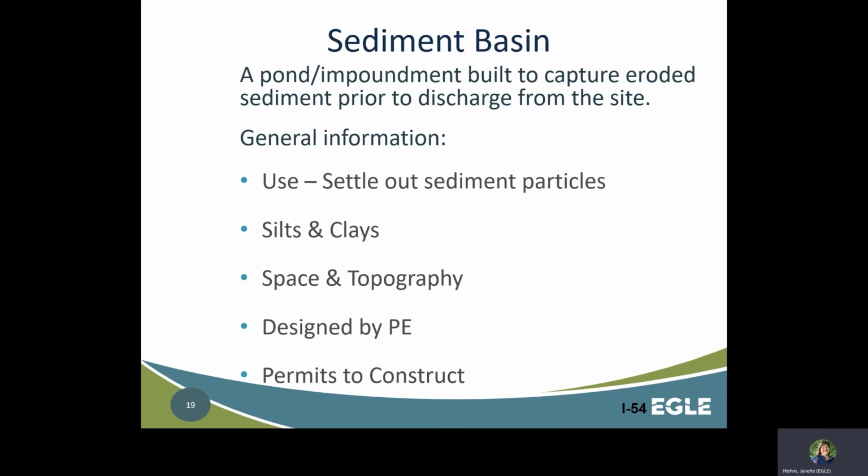Sediment basins can be effective for removing particles of sand and larger particles of silt. But what about smaller particles, including silts and fine clays? These small particles of sediment do not readily settle out in a sediment basin unless they have some extra help. Chemicals called polyacrylamides or PAMs are often used when fine silts and clays are present at the site of earth change. PAMs may be added to the sediment basin in order to help these particles to settle out in the basin.